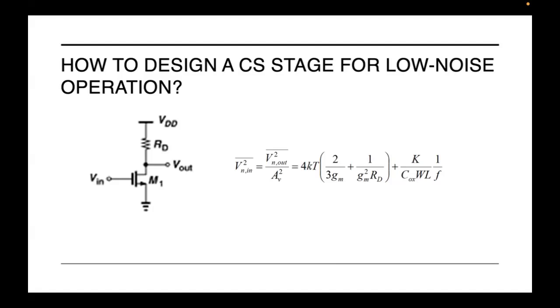So for example, when we go with ultra low threshold voltage applications, typically used in sensing applications, when we have V threshold small, that means that you can operate with a VG small. This is something good in terms of the sensing application, but this will lead to a very low GM, which means a high level of noise.